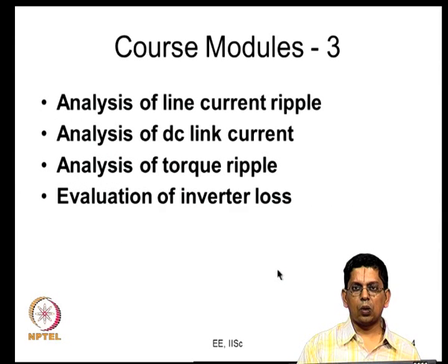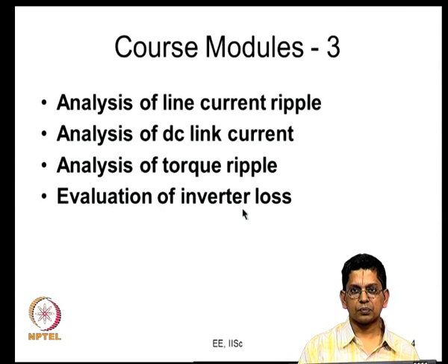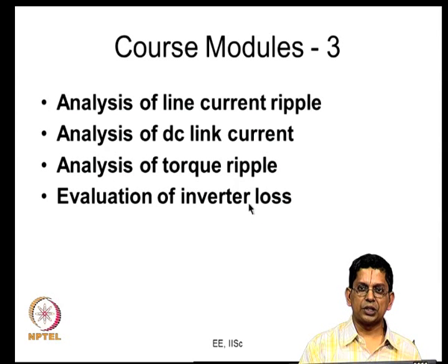So, let us go on from that. That is the second set of modules, and the third set of modules has been more into analysis. Earlier the focus was more on generating the given amount of PWM waveform and maybe enhancing the DC bus utilization, that is, for a given amount of DC voltage, how much AC voltage you can produce. That is one of the reasons why we went in for common mode injection and so on.